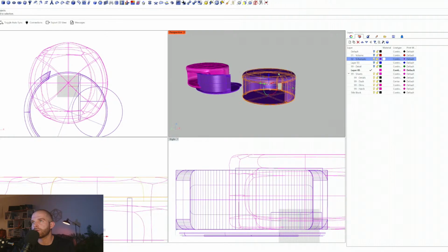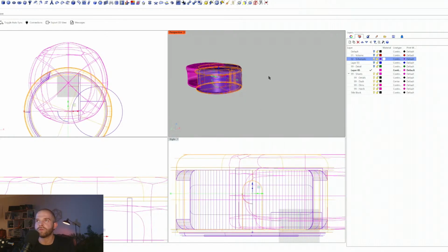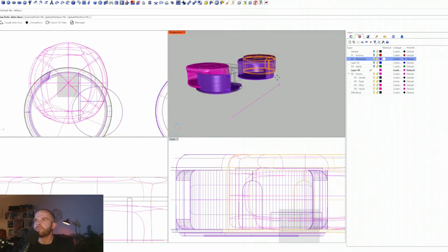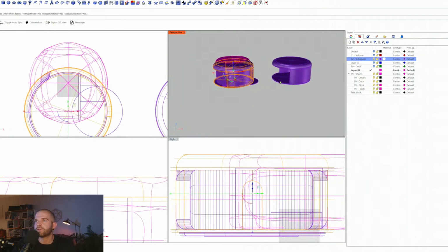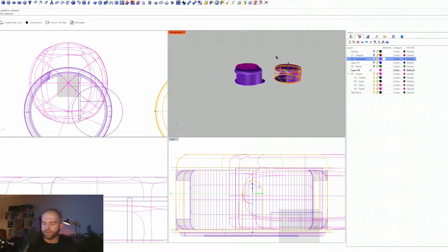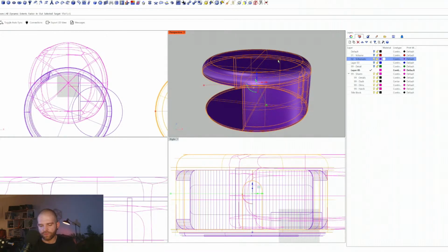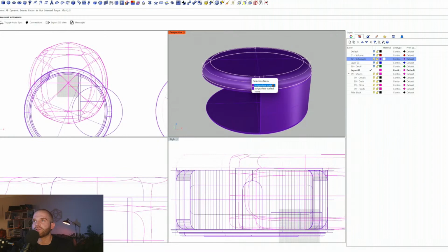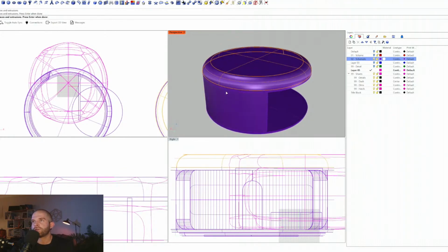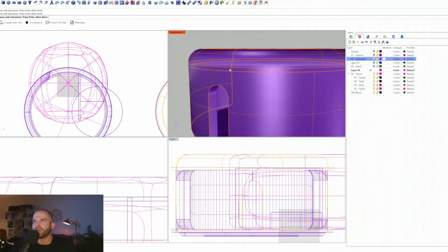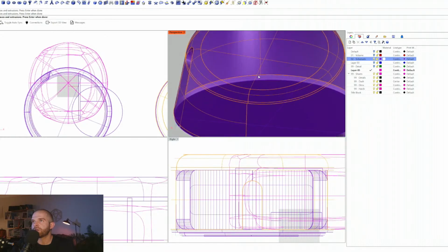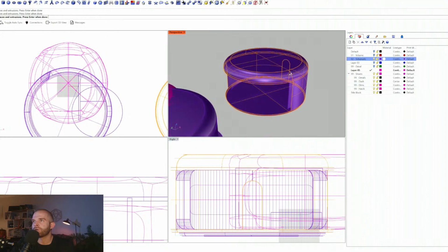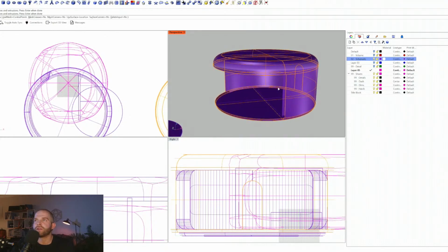And we can do, oh, I was meant to copy. And copy them over. And we can do ToSubD. So if we do need a perfect cylinder like that, oh, we have to do faces. We can select these faces or just all the outer faces of this thing. Cool. And then hit enter.